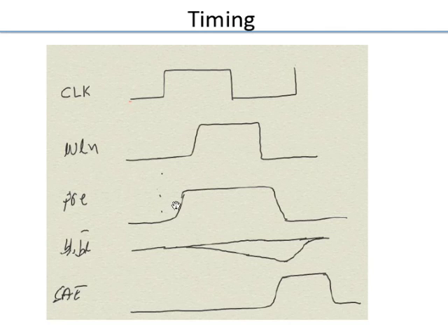And if you recall, the memory cell is connected to the bit lines which are pre-charged to a high value. Around the time you turn on the memory cell so that the access transistors start discharging the bit line, you want to disable the pull-up. Whatever is holding the bit line to VDD, you want to disconnect it so that the bit lines become floating, or at least are not held high. Otherwise the memory cell will not be able to pull down the bit line. So that is what is done here.